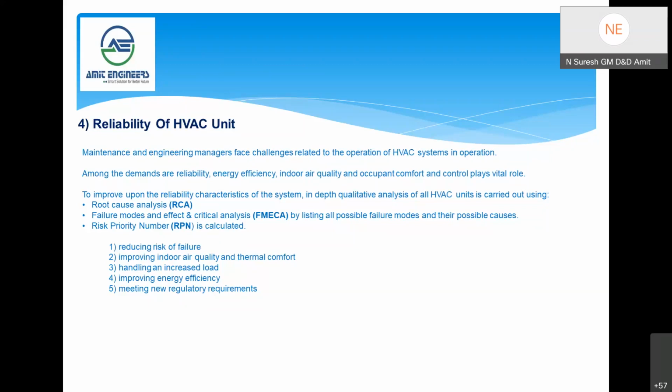Is it something like you collect the failure data and, on the basis of that, periodically do these analyses? Yes. What is the methodology? Does the maintenance side have to do something? No, maintenance basically logs the faults and failures. Our service team is in touch with them and collects that data, and it is communicated to the head office, and we look at the MTBF, the mean time between failures. Is the data collected, or already logged in the system?